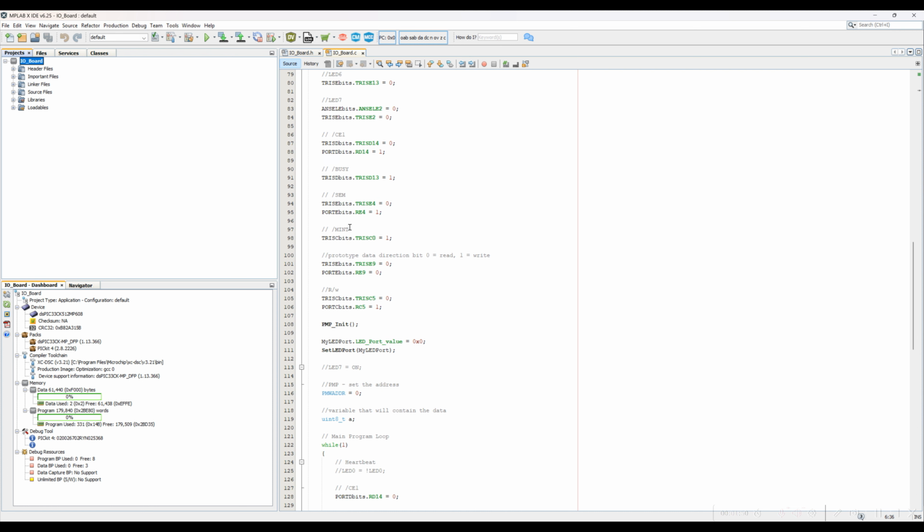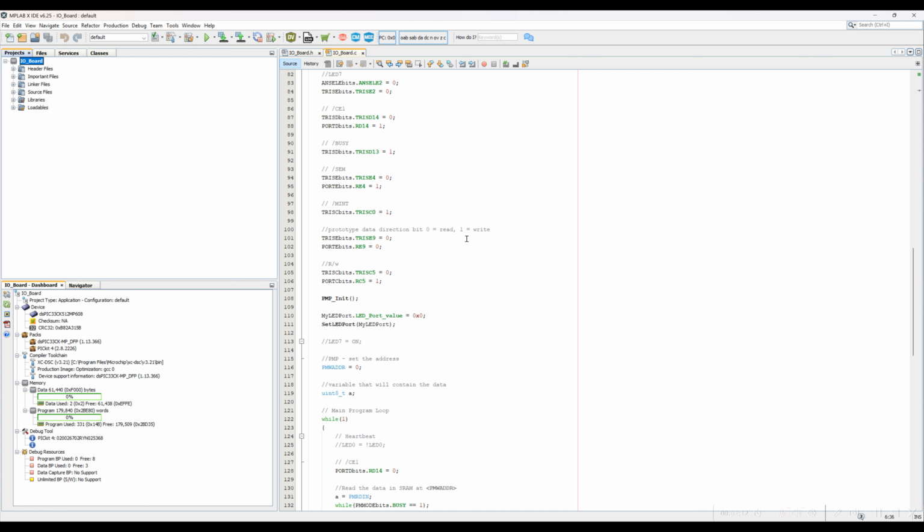And then there's the memory interrupt. That's another subject for later, but you can generate interrupts in both directions through the SRAM by writing to certain parts of memory. So we can get into that later too. This is just for the prototype board, where we have to flip our bidirectional transceiver buffer around in the next revision, and this takes care of that.